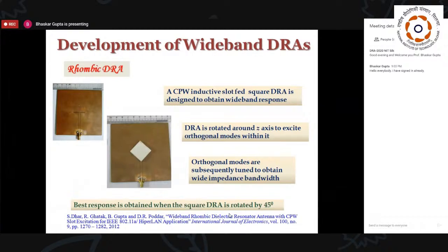Well, the antenna here is placed on a metallic ground plane on which you can see a CPW. Look at the structure on the left. The CPW is meant to feed the antenna. Usually, all the DRAs are just mounted like that on the ground plane. They are not left aside in free space, but that doesn't contribute to conduction losses, because essentially the field is confined in the radiator. But we have to do that for mechanical stability, for mounting purpose.